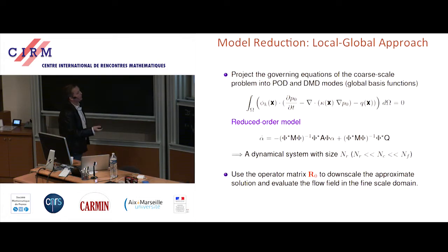So again, the idea here is fairly simple, which is basically our final reduced order model is going to be the projection of the coarse scale, generalized multiscale finite elements onto a subspace given by these modes. And in the end, we end up getting this reduced order model, which could be 1,000 degrees of freedom, that gives us a sufficiently accurate representation of the overall behavior of the system.